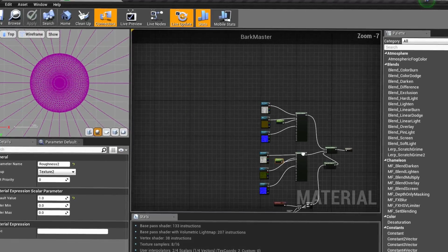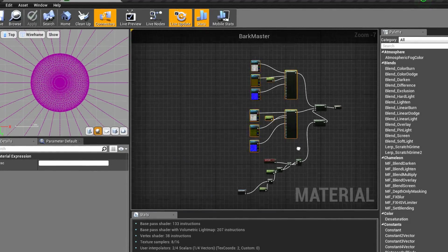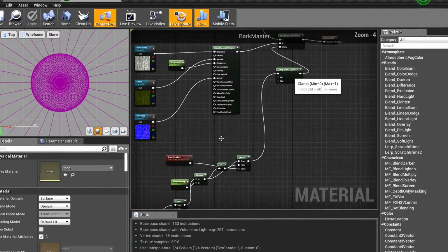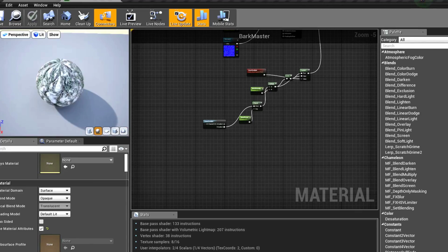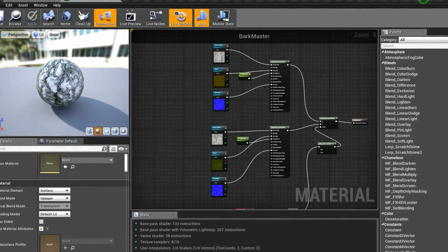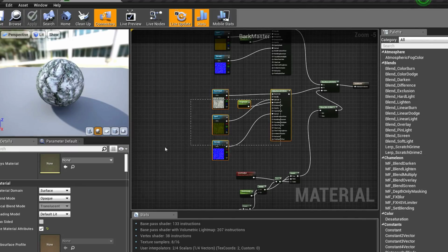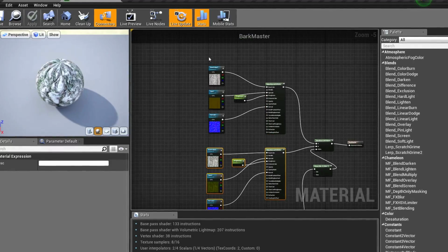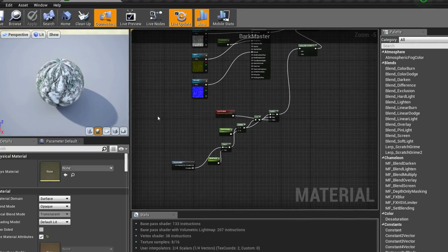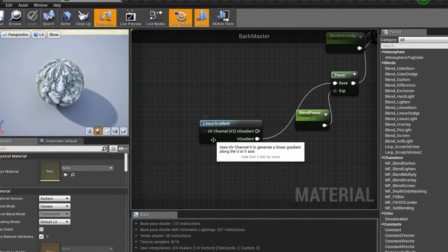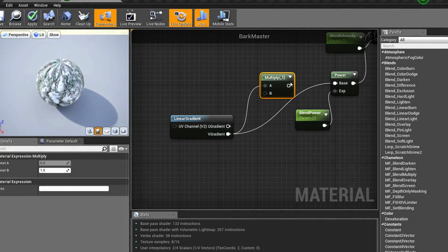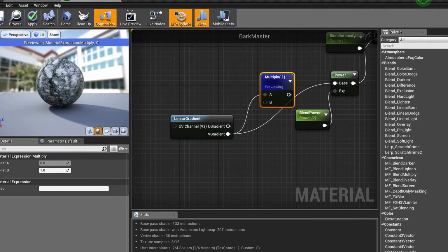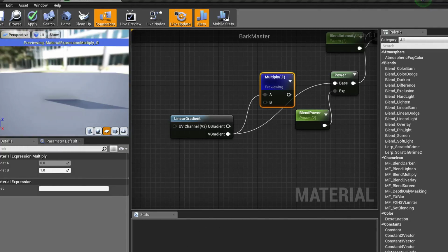Alright, so now that I've got this set up, I want to start working a way so that I could blend this blend texture at the bottom, and as I go up this should appear. So for that I'm going to use a linear gradient, a V gradient in it. So V is vertical. Start previewing node. I want to see this.